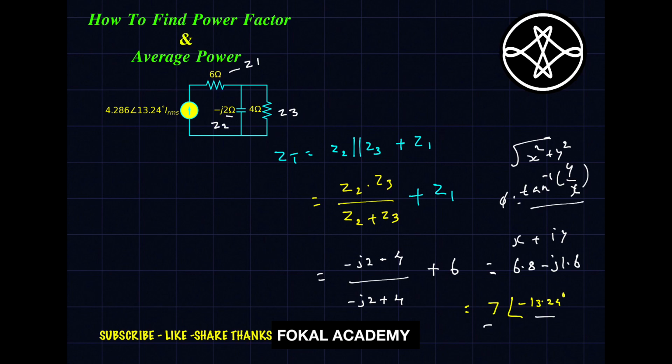So power factor PF equals cos theta. So what is the theta here? This is not the theta value, this is the theta value. Both values are the same, but why it is this value, let me explain. Theta means nothing but the phase angle of voltage minus the phase angle of current. So the phase angle of RMS voltage minus the phase angle of RMS current is theta.